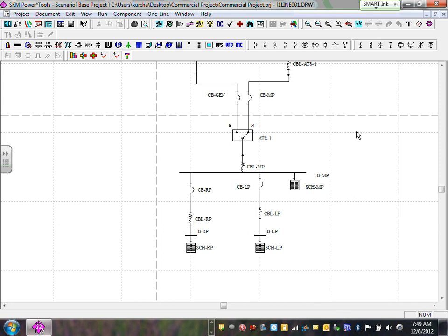So that's what I'm going to do. Now to do the coordination, here's what I would like you guys to do. We can do the coordination between the overcurrent protection device, the mains, and these 2 circuit breakers easily. But I need to do two more coordinations that are vital for this project. Look at the largest single standalone motor in this project. Was it the air handling unit or the chiller? Chiller. Okay.